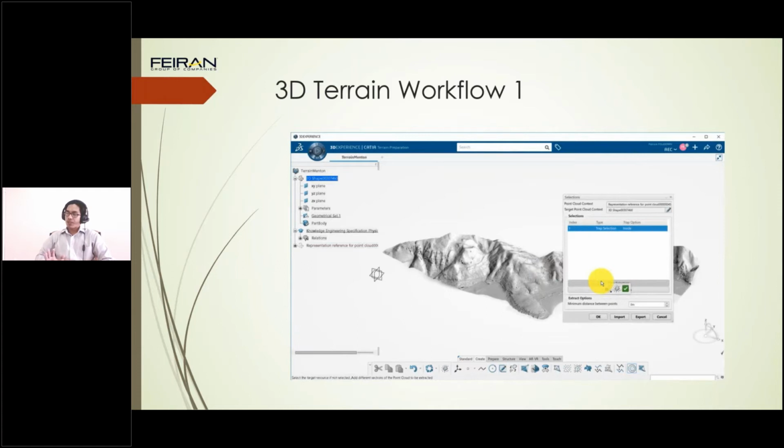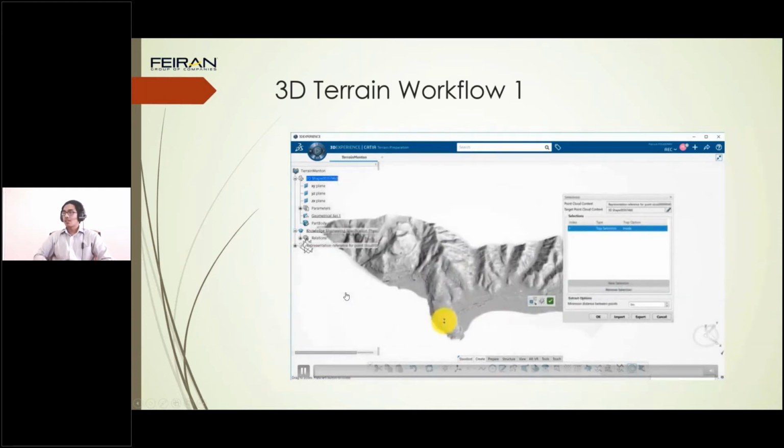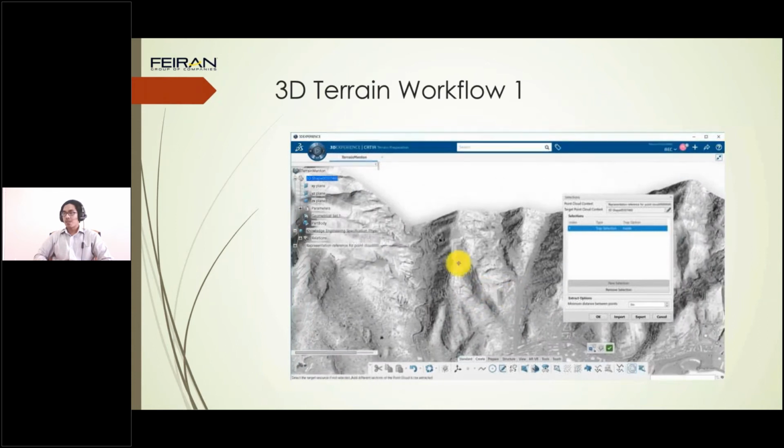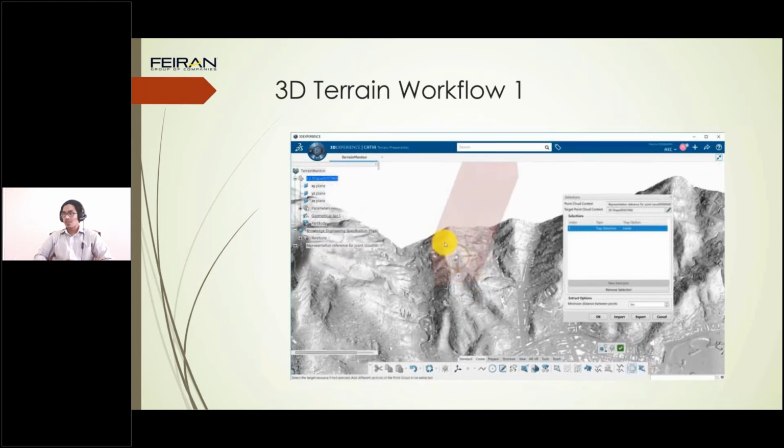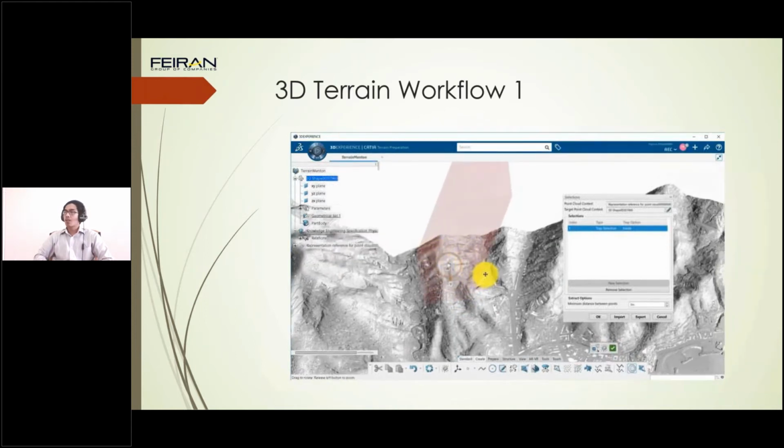So we tend to overshoot our area of interest a lot, since we need to understand that the way LiDAR is performed is flyover. There are some aerial maneuvers by the airplane or drone, etc. So we need to further reduce our portion of cloud of points here, specifically focusing on our area of interest only. Although the cloud of points is very big and covers a lot of area, we are only concerned about this area of interest, which is very small compared to the whole cloud of points.